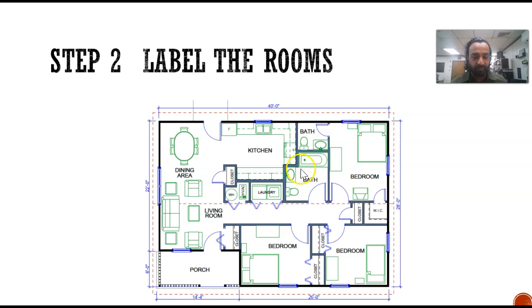Okay, what about this bathroom here? This bathroom is not facing anything to the outside, so it does not require to be heated. It's going to absorb heat from its surroundings, so we do not have to heat that bathroom. What about this closet? This closet, yes, because there's part of the wall. It's not going to be a heated closet, but the wall will be included in either bedroom's heat loss.